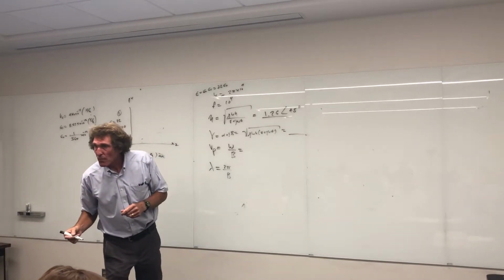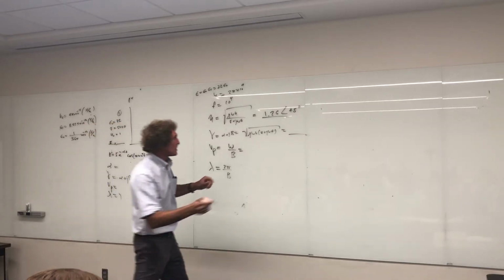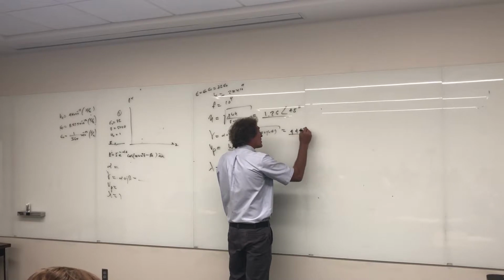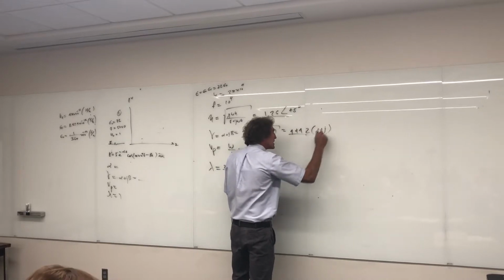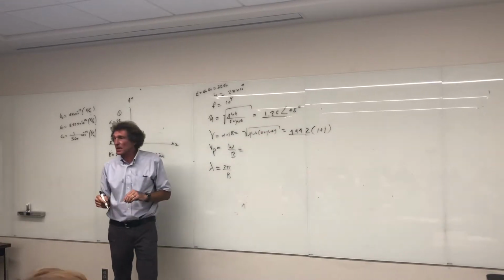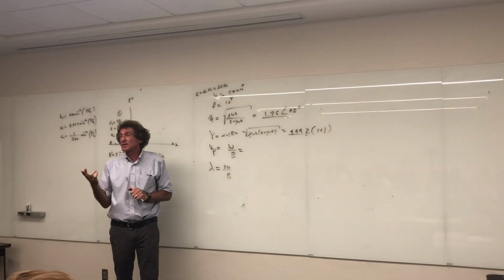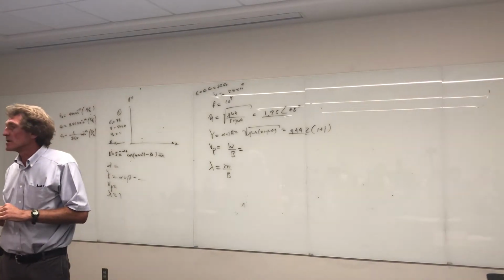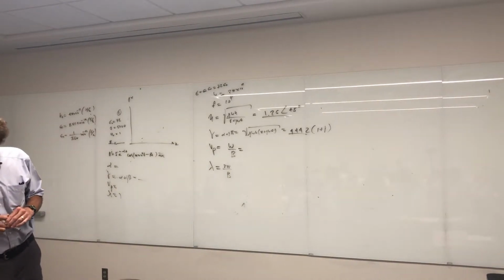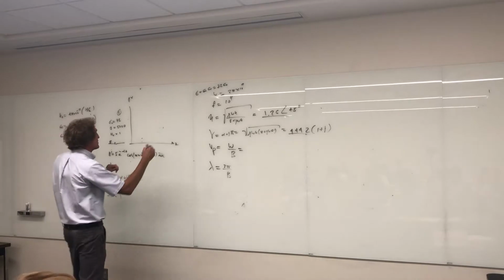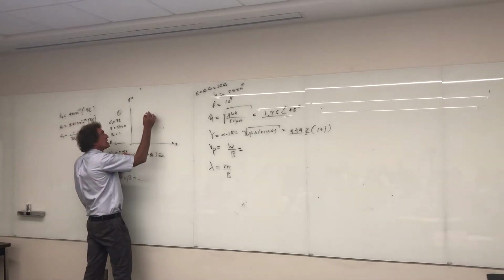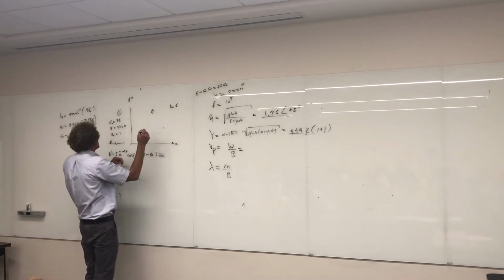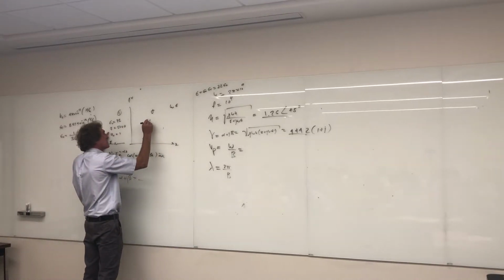4,442. All right. So it's 4,442 times (1 plus j), because here alpha equals beta, isn't it, class? It's a good conductor. How can you tell it's a good conductor? Anyone? Alpha and beta. Well, yeah, that's an aftermath. But the way you see if it's a good conductor, take a look at sigma and compare it to omega epsilon. Now, sigma in this one is 5,000, right?